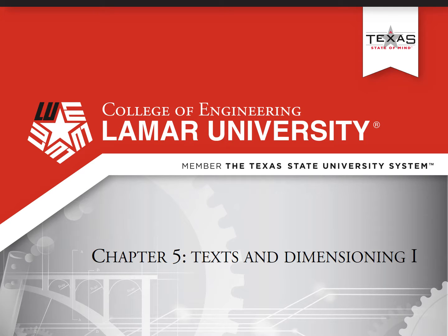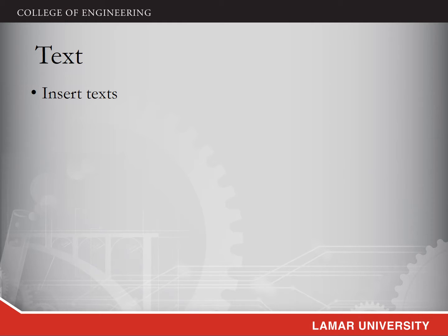In this lecture, we'll learn how to insert texts in the drawing file and how to identify different types of the dimensions of the drawing. Basically, AutoCAD provides two different methods for you to insert texts in the drawing file.